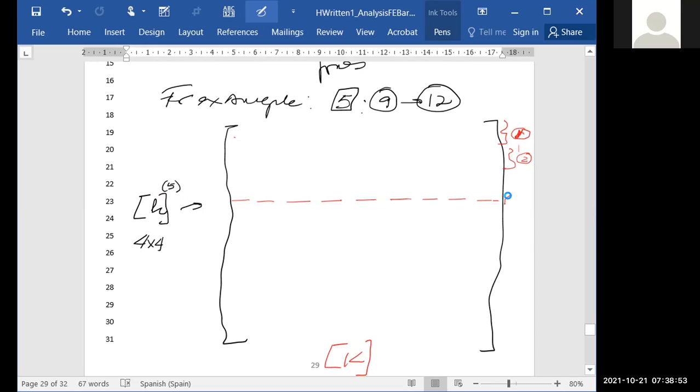That is the first row. The second is plus 1. So this is the number of the joint minus 1 times 2, because you have 2 degrees of freedom for every joint. And the next one, of course, is that number plus 2. So it's this plus 1 more.